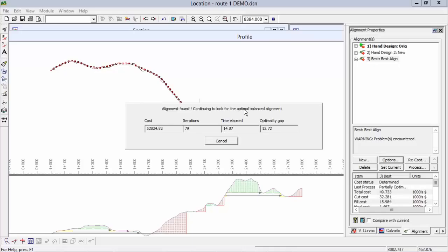So here, the optimization proper is actually being done. This is a process, as I said, that takes a bit more time. As soon as you have a solution here, you can cancel anytime you want, and it's just a matter of how long you are willing to wait. This last number here indicates how close you are to the best solution. Here, it means that you still have 10% of possible improvement. We don't really have too much time, so I'm just going to cancel it right away.